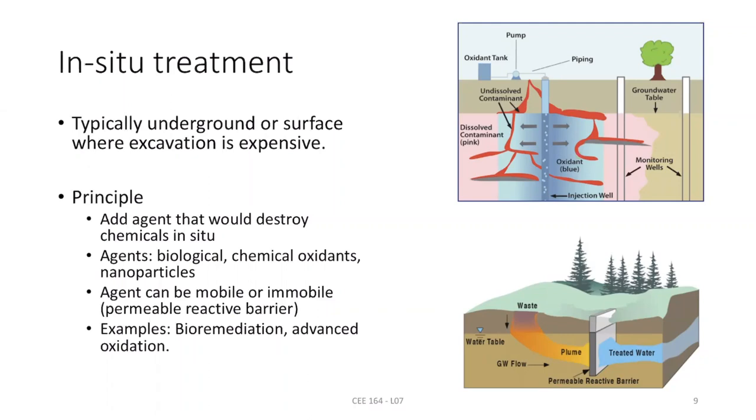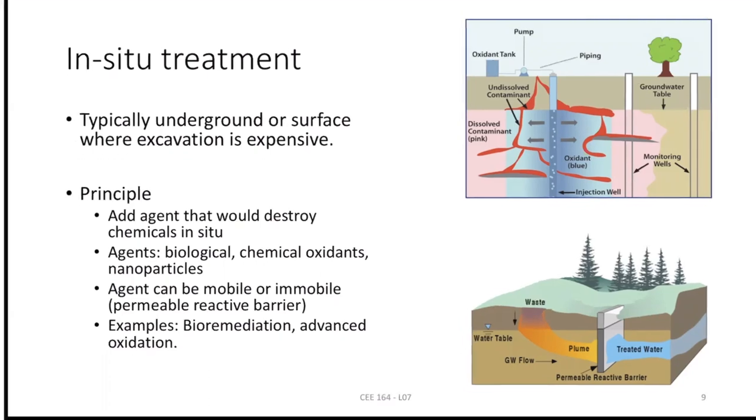And a lot of times they also mix this activated carbon with a biological organism like bacteria, and inject them inside. The idea here is that this activated carbon will capture a lot of nutrients, and the bacteria will eat them away because they are sitting right there, and that way the activated carbon becomes renewed to remove more pollutant. So these are different types of technology. When I hear your outline or your site problems, then I'll suggest some of these for you. That's why this meeting is essential to discuss all possible treatment options for your sites or for your problems.